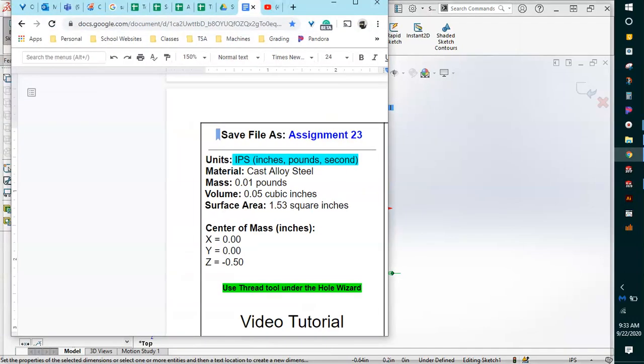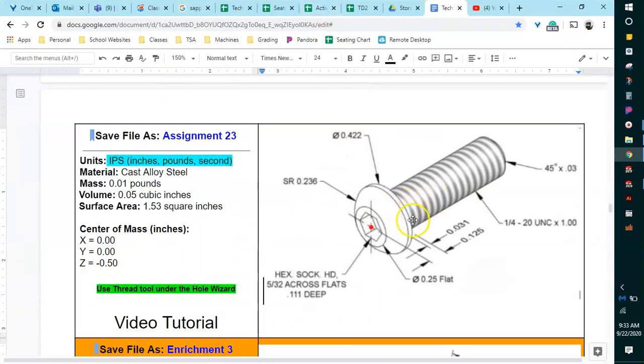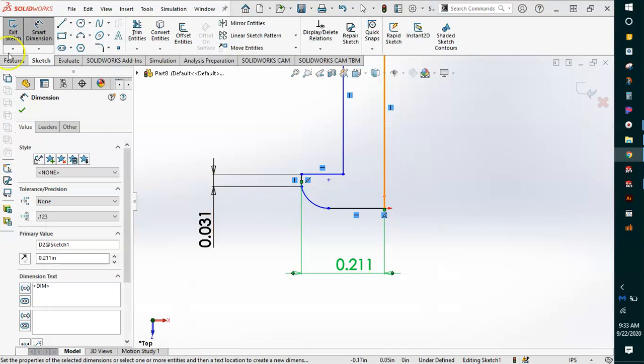Now, if I pull this back over again, working on the head still here, it says from that flat part to where the origin is 1/8 of an inch, 0.125. It says the flat part itself has a diameter of 1/4 of an inch. So again, if we're only working on half of this, that means it's going to be 1/8 of an inch. So we're going to be putting in that number, 0.125, two times here.